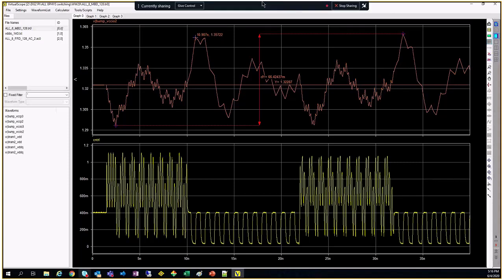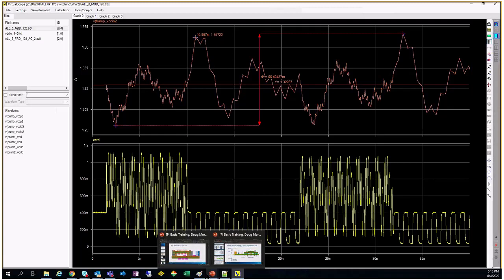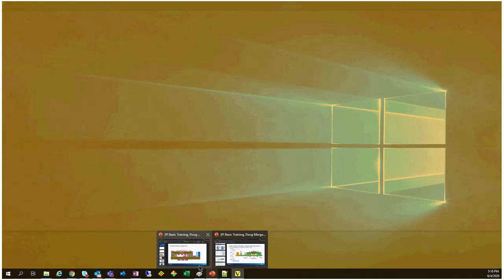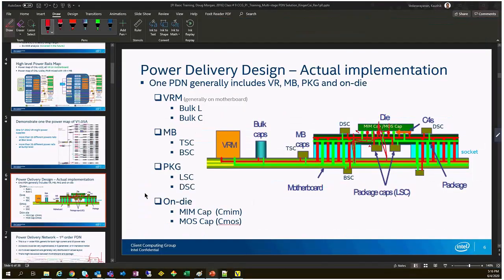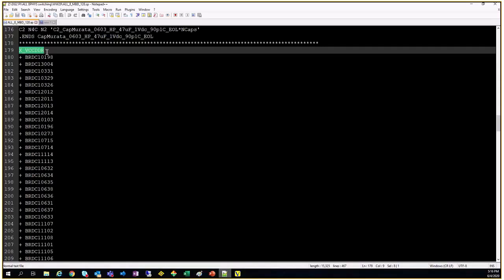That's it. So for this, that is why we form ports on the capacitors. We form ports on the cap. So if you look here, I will take the SPICE network. Now I will show you how we build a SPICE network. So first thing, if you notice, I have listed something called x underscore VCC DDR. Okay. So this is how you list. This is something called a subcircuit.